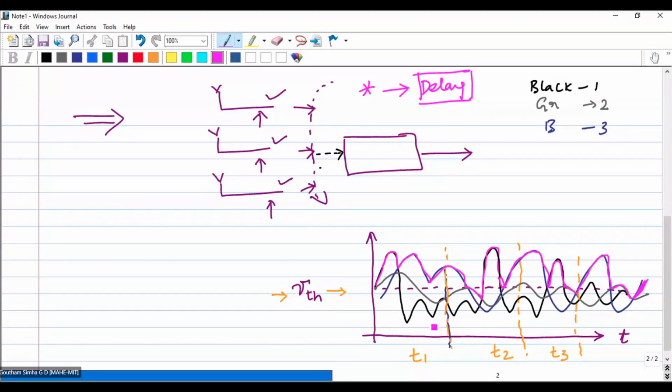So the level crossing rates have been identified as the threshold, and you are being moved across the SNR based on the highest signal. Now, average of the signal has been changed. That is the important aspect of your selection combining. Average of the signal has been changed compared to individual branches, isn't it so?